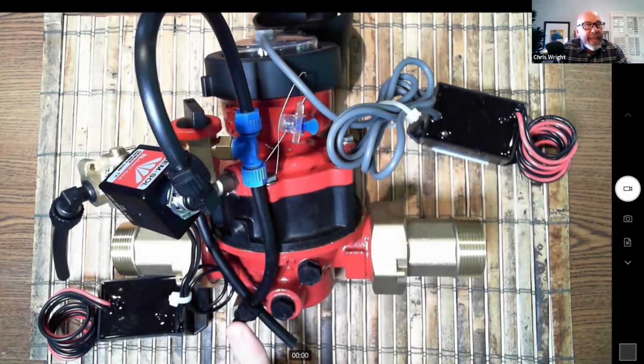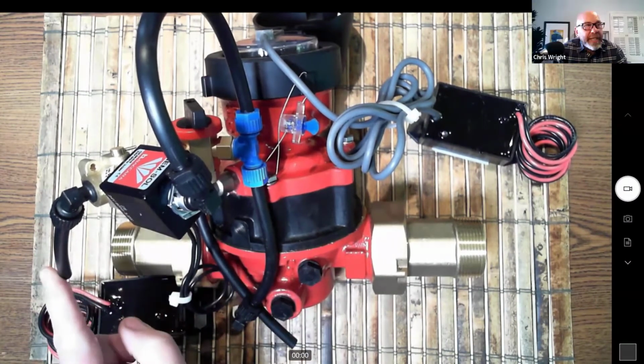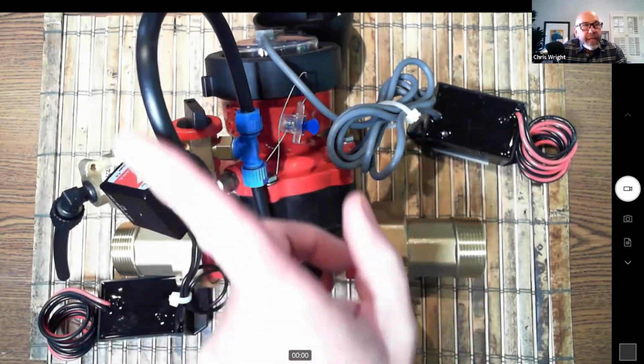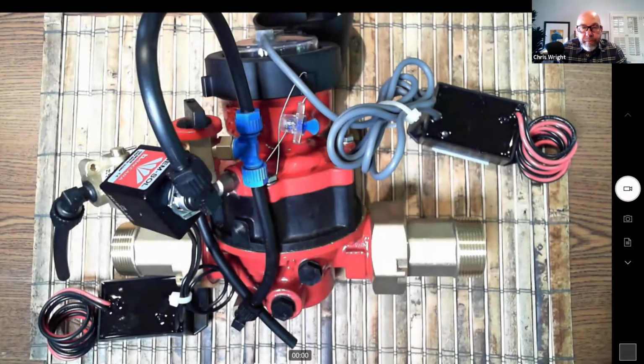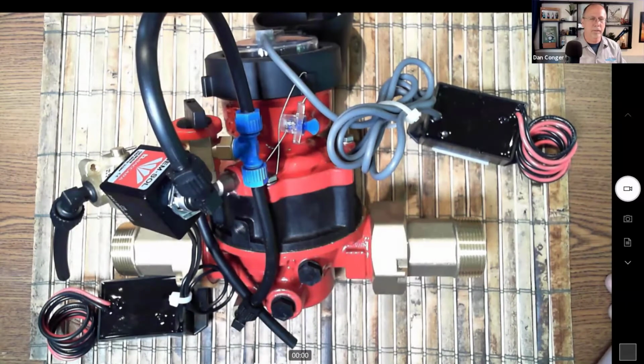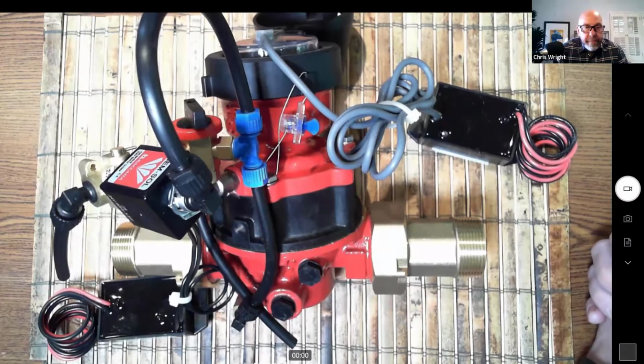If that tube were to vent to atmosphere shortly after it comes off the top of the solenoid, then it would be normally open. Which would mean what? If it's in a room, it'll squirt a little water if it activates. Right.